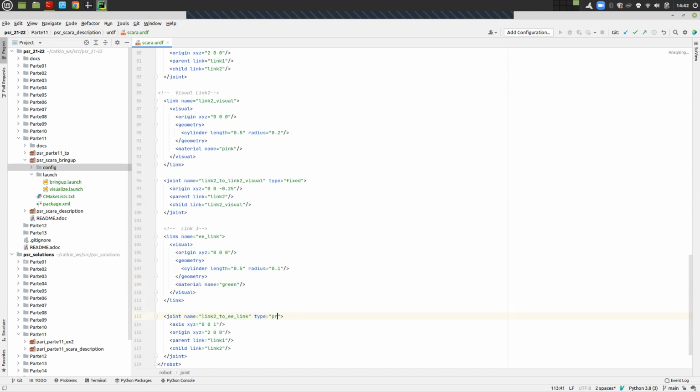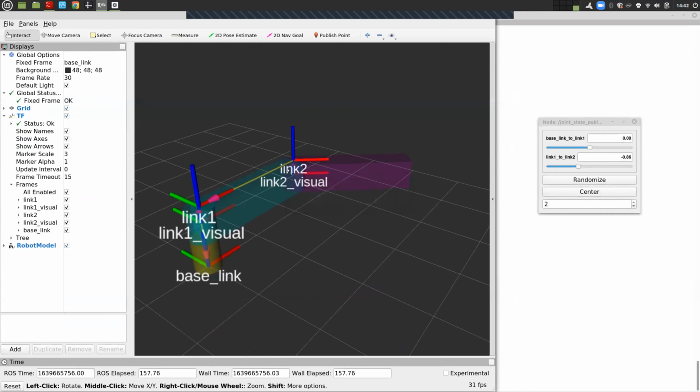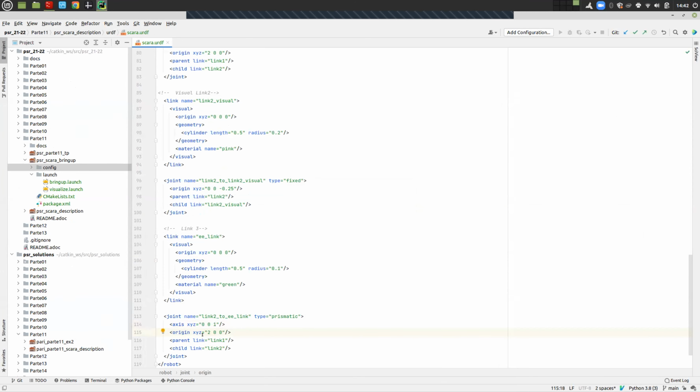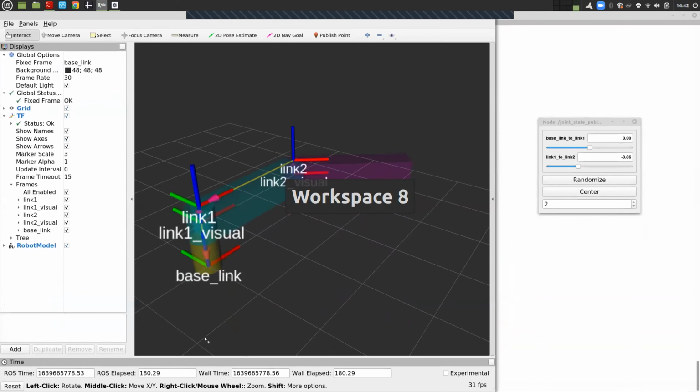So I know this is going to be a prismatic joint. The prismatic also has an axis, it's like a telescope over the Z axis. The origin here, with respect to link 2, will have to be all this length here. So this is the length of the box, which is 2. So I think that is okay. And also the Y and Z, I think is okay. So EE link. What I'm not sure is okay is this part, but let's see it afterwards. Go ahead, Jay.